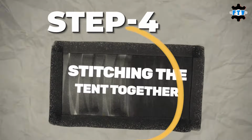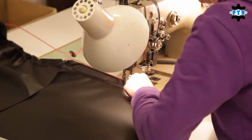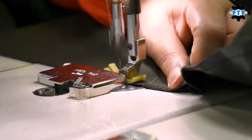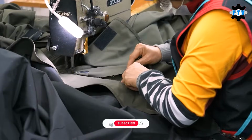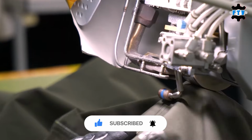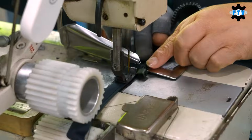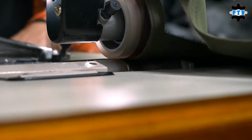Step 4. Stitching the tent together. Once the pieces are cut, then it is time to sew these pieces together. Industrial sewing machines do the work in order to create seams that are capable of withstanding natural conditions that may adversely affect them. If the seams are not factory sealed, then you will also notice that many tents also have taped seams. This is a process where a waterproof tape is applied over the stitching to avoid water penetration. Other functional enhancements, including zippers for doorways, mesh for windows for airing, and guy line tabs for rigidity, are incorporated at this time as well.